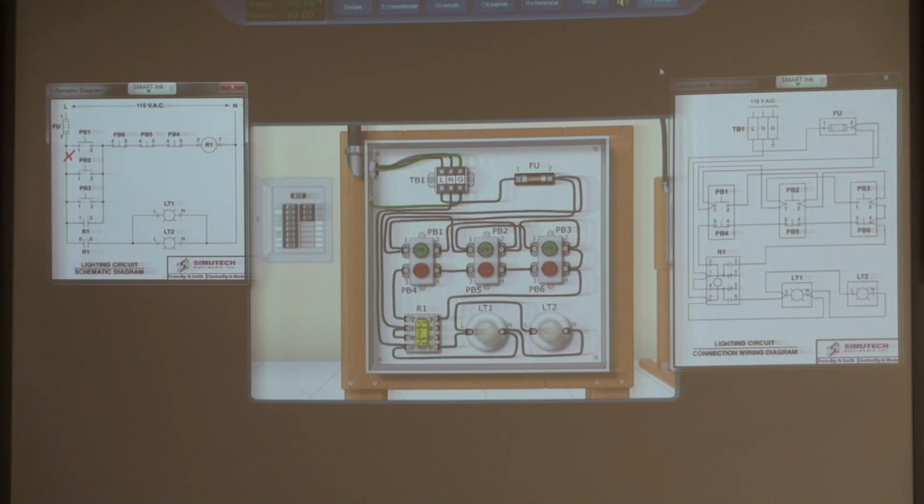Mechanical relays fail all the time, so you run back, get one, be a hero, and dadgummit, that didn't fix it. So then what you should have done the first time is measure whether pin 3 had 115 volts when PB1 was pressed, and whether pin 6 had 115 volts. Both pin 3 and pin 6 should get 115 volts when the PBs are pressed.